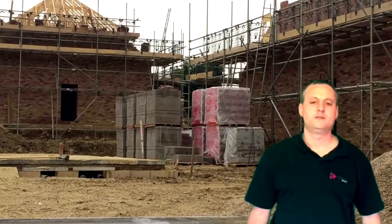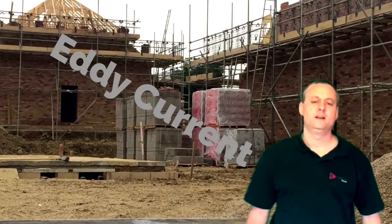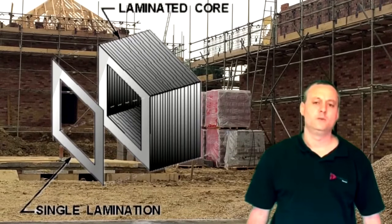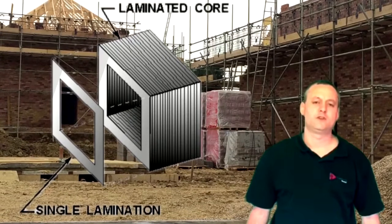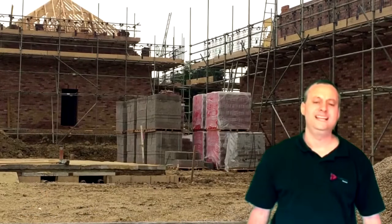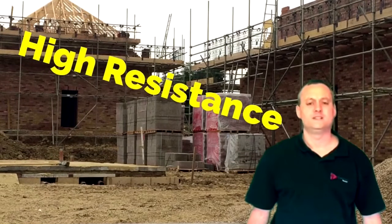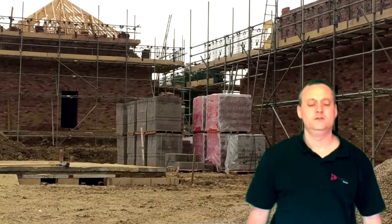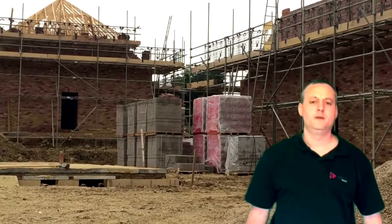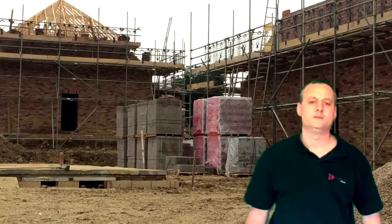We said the core itself can have a loss in it, and that is an eddy current loss. And we said that we overcome this by cutting the core or slicing it into what we call laminations. So each individual slice is insulated from the other individual slice, and therefore making the core easily magnetized, might be soft iron, but very high resistance, making the actual eddy current that's induced into it considerably smaller than a core that wasn't laminated. We mentioned hysteresis and copper losses on the way through, but they won't appear in our level 1 or level 2 exam.